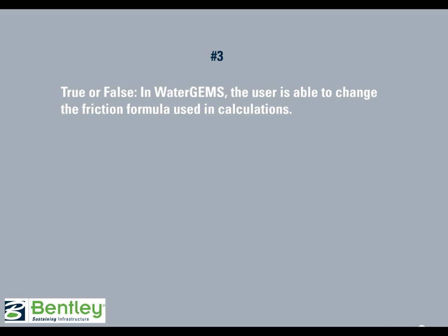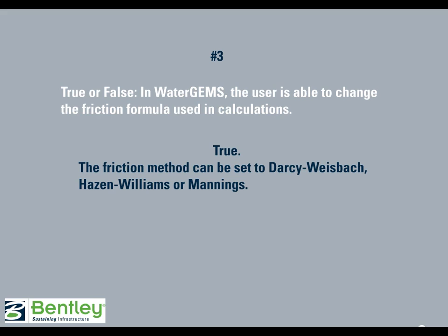Number 3. True or false? In WaterGEMS, the user is able to change the friction formula used in calculations. And the answer is true. The friction method can be set to Darcy-Weisbach, Hazen-Williams, or Manning's.